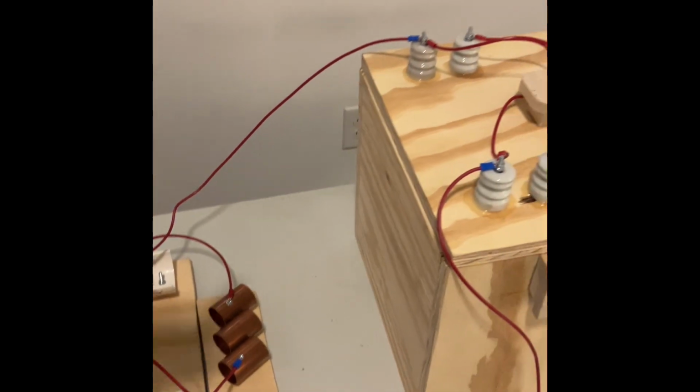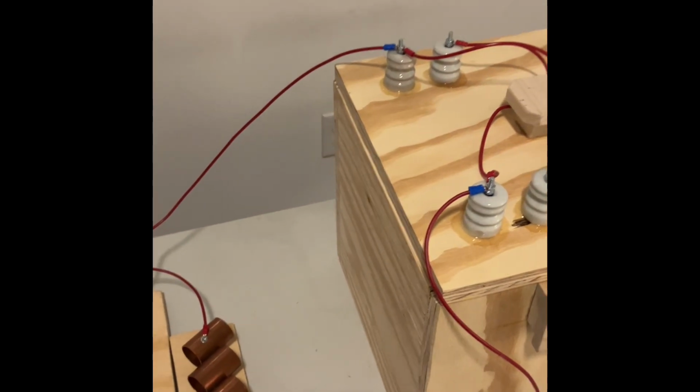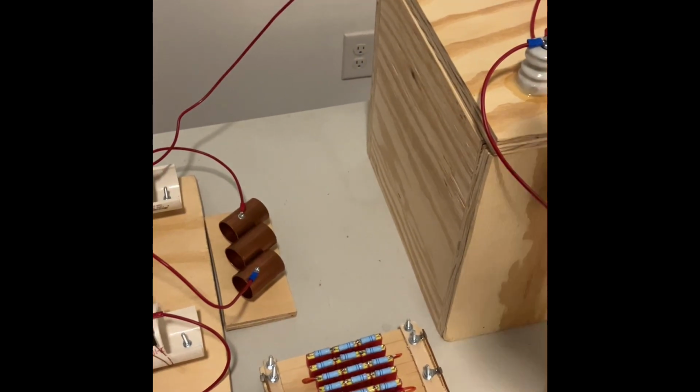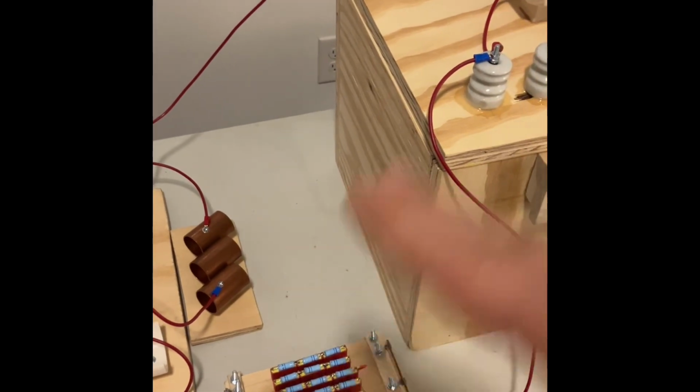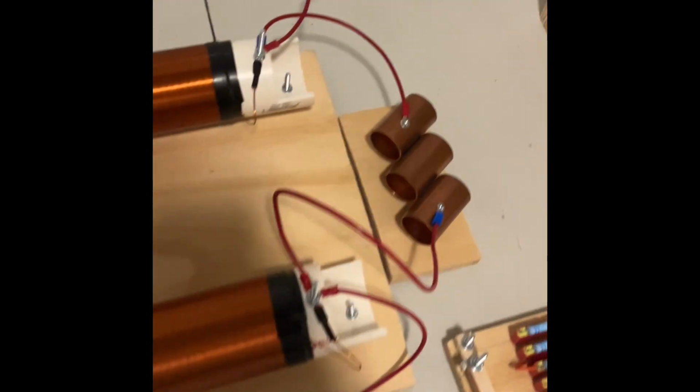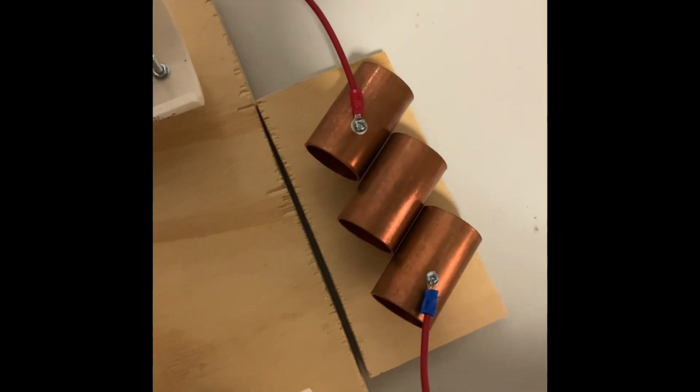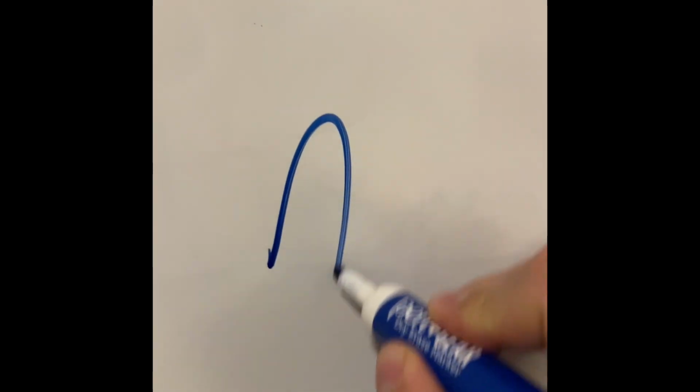So every time it breaks, that is sending a current impulse into this primary side of the circuit. And with the inductance of the primary and the capacitance here, it's going to oscillate for a little bit as it dies out. So each time that we see a little spark break across that gap, we're going to get some sort of waveform that looks like this.